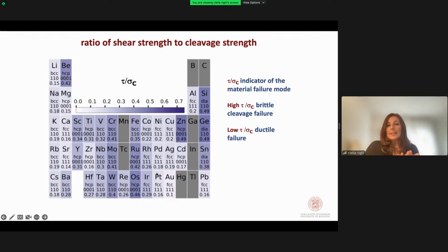So you can understand that by analyzing the database obtained by means of high-throughput calculations, these general relations can be identified. These are just a few examples, but relevant because these parameters can also be used in macro-scale models, where very often the material properties related to the microscopic details are not taken into account, and parameters such as the adhesion and the ideal shear strength are empirical or just a qualitative description.